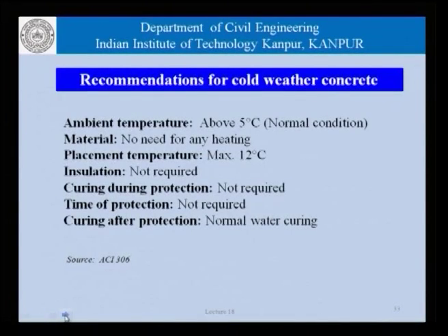Continuing with our recommendations for cold weather concreting, if the ambient temperature is more than 5 degrees, the conditions are more or less normal. We do not need to heat the materials. We can have a limit on the placement temperature. No insulation is required. No curing during protection is required. Time of protection has no specific limit, and for curing after protection, normal water curing is all right.